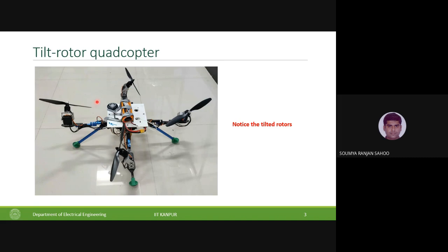It doesn't change. Now, in a conventional quad, you want to control x, y, z, which is the translation, and roll, pitch, yaw, which is the attitude. So you want to control 6 variables, while you have only 4 actuations, which are the four thrust vectors. So it's an under actuated system. That is why there is a coupling between the attitude and the position. So we say that you can only control x, y, z and the yaw angle or the heading angle, while giving away the roll and pitch angle, making them dependent on whatever x and y is commanded.